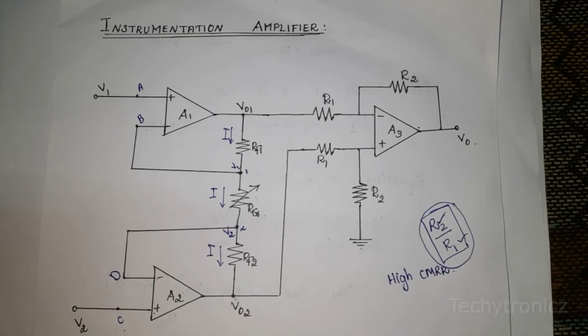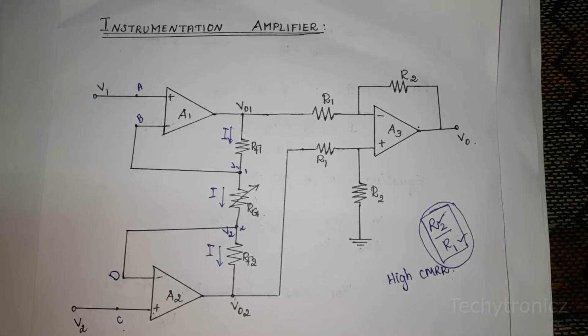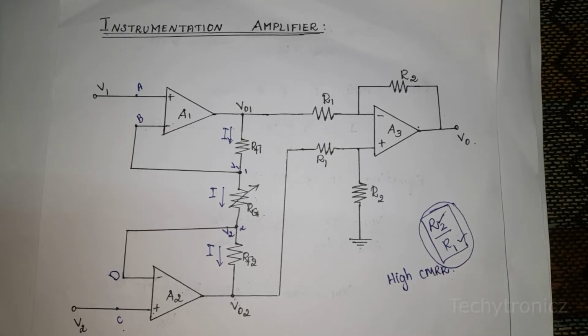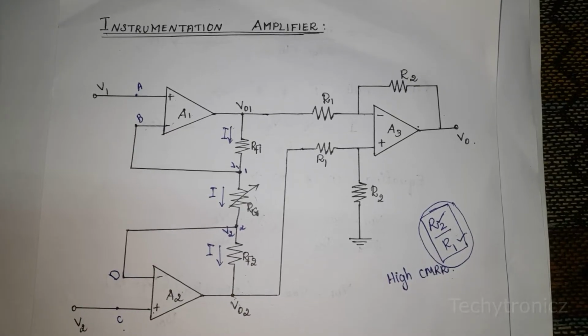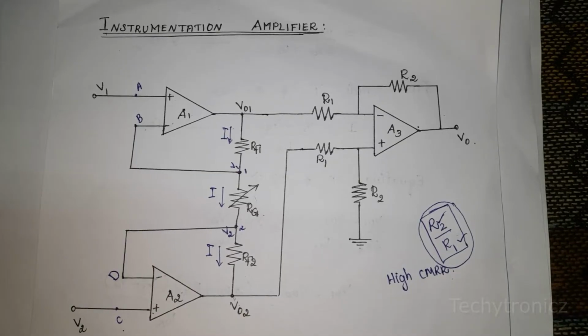Hence, a special amplifier is used to amplify such signals. The special amplifier which is used for such low level amplification, with high CMRR, high input impedance to avoid loading, low power consumption and some other features, is called an instrumentation amplifier. The instrumentation amplifier allows one flexibility, that is, the gain can be changed by changing only a single resistance value.